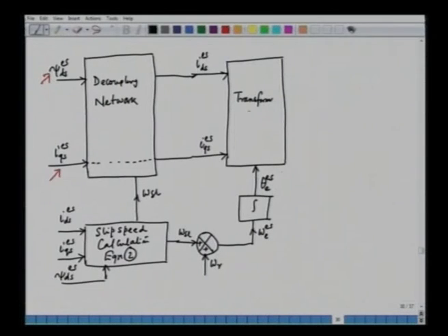And then after this transformation from IDS and IQS using theta E, what we obtain here is the reference 3-phase current IA, IB, IC. They are the reference currents. So, we can denote them as IA star, IB star, and IC star. And the reference currents that we have can be impressed on the machine using an inverter.